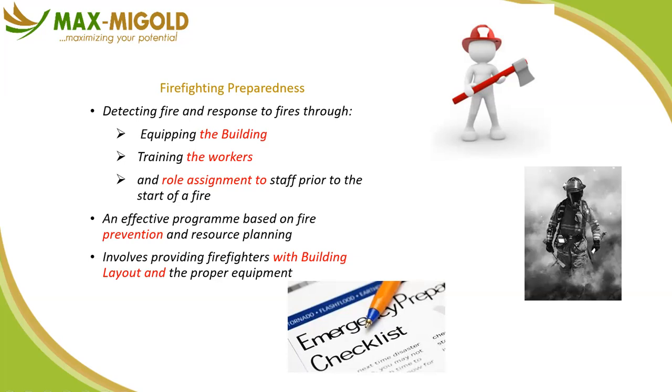Conducting a fire drill is a form of training. So you must conduct at least one fire drill every year. Let me announce to you that I'm not saying this because we want you to feel good. That is the law. The Nigerian Fire Building Regulation 2013 has requested that at a minimum one fire drill must be conducted in a year. For some of us, we even do two. Evacuate the building and see how the response is going to be, because on the day of the fire, people only behave the way they are trained to behave.